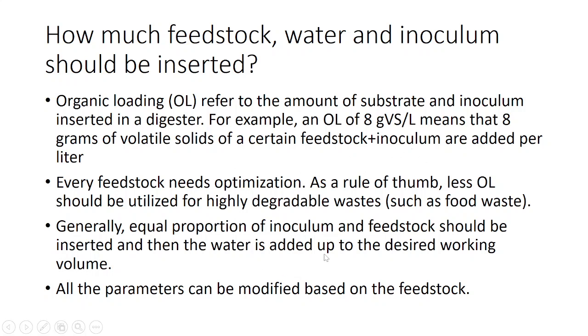So as a rule of thumb, again, the same proportion of inoculum and feedstock should be used. But of course, you can vary this proportion. For example, 1:2, 2:1. You can do different experimentation based on your own feedstock, and then define the desired ratio for your operation.